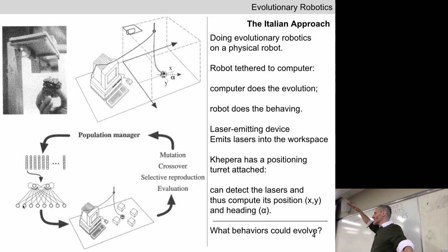They're going to get the sensor values back from the robot through this tether. They're going to plug those sensor values into the neural network, propagate those sensor neuron values through to the motor neuron values, get those motor neuron values back, turn them into torques, send those torques back along the tether to the Khepera robot, and those torques are going to be applied to the two wheels.